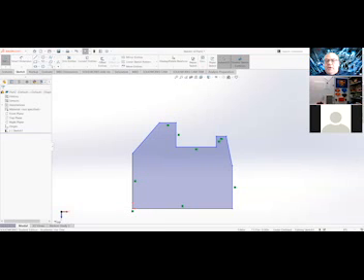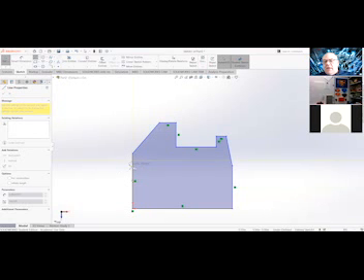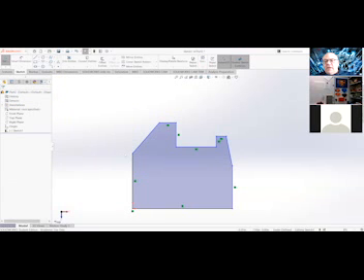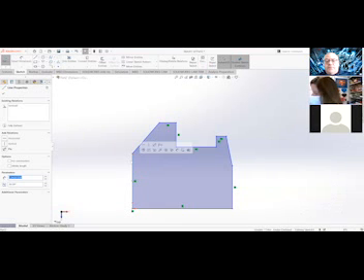So kind of keep your eye up here. If I look at where my line icon is, the top, when that's on, it's grayed in. And then if I select a line, it wants me to draw on that line, and so I have to fight that a little bit. If I turn that off, and you can do either escape or right click and select, then you should be able to pick that line, even if it is already constrained.